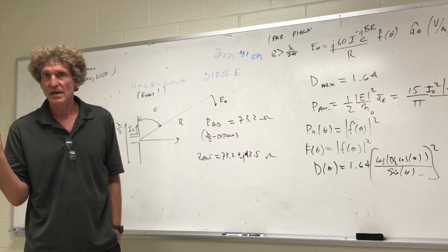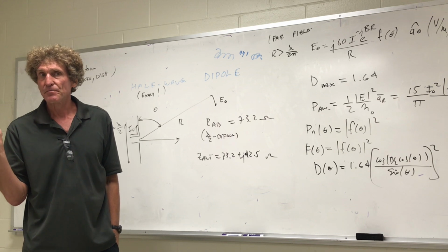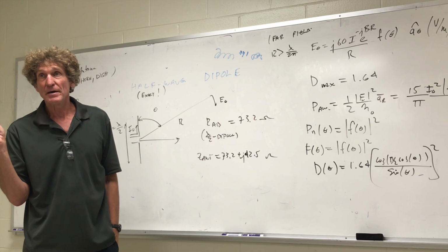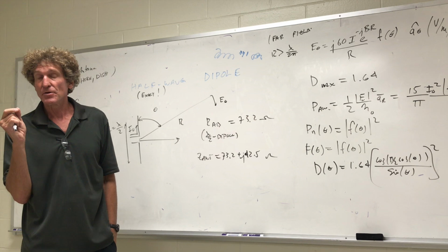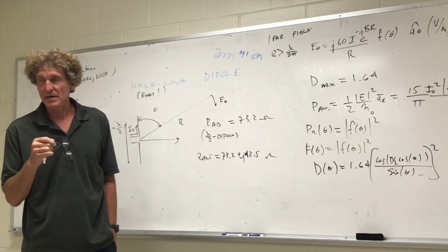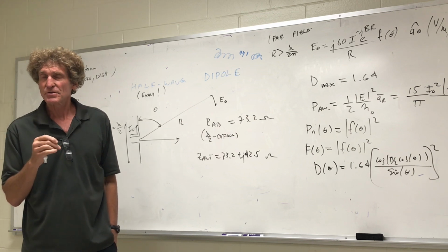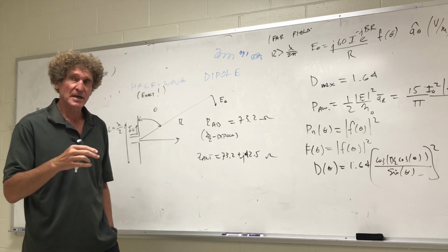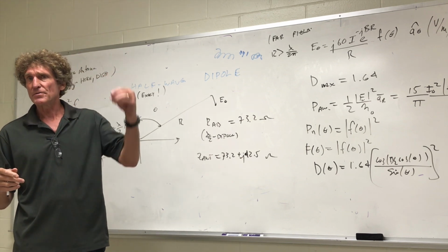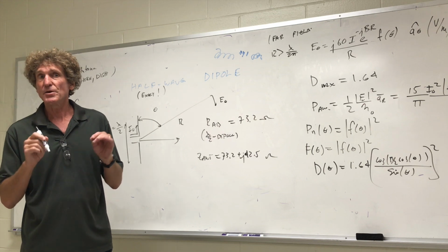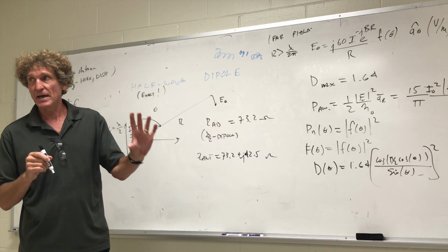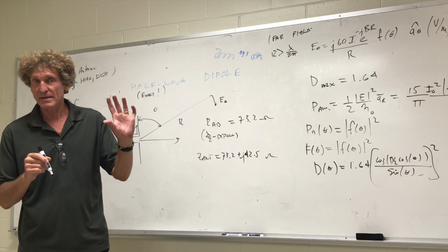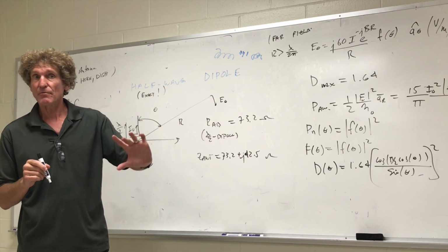It can change. And if you really want exact values, you've got to have a ratio. You really need to know the circumference of the wire and the wavelength that you're using, and there are formulas for this that you can look up. But there are tricks to this stuff. And in my EMC class, we go through all these things you need to consider for design. And when you're actually troubleshooting something, when there's a problem, you have to look carefully at the radiating part of it. You have to look at what the antenna is actually radiating, not what they say.